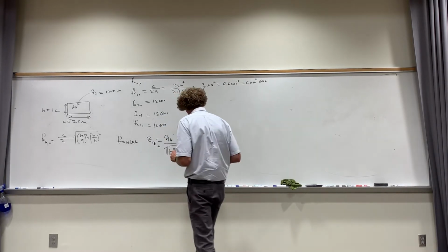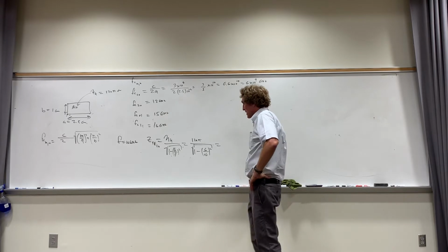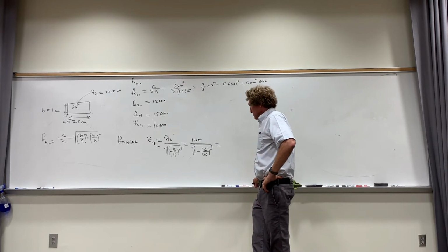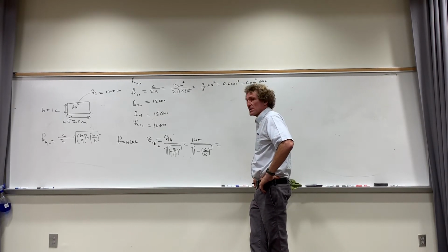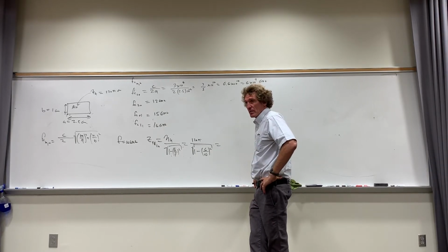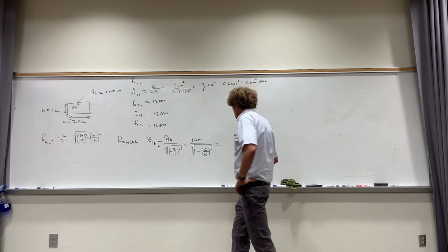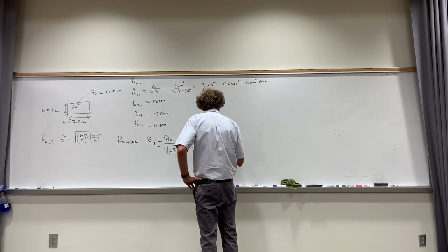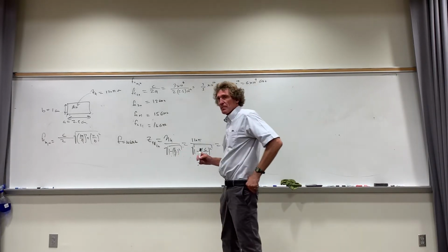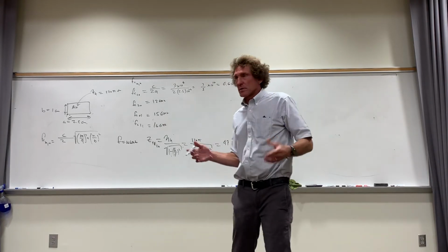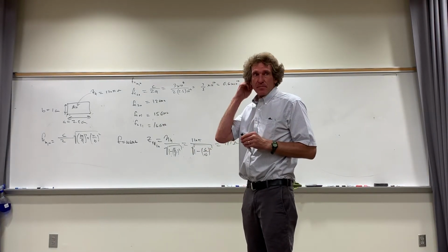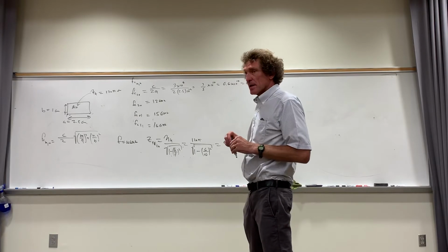So what's the characteristic impedance? This is for TE. This is a very common thing that I'll ask. So 471 ohms. Is it 470? 471 ohms? Anybody else second that? Yeah. All right, so it's greater than 377, right? Not by a whole lot, but by enough.